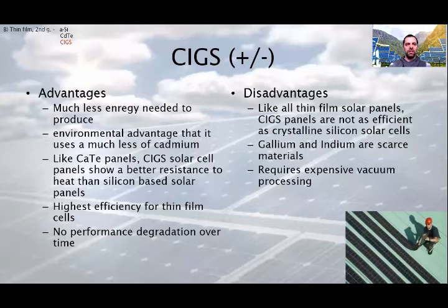As always, we evaluate its pros and cons. First, let's see the advantages of CIGS. The active layer CIGS can be deposited in a polycrystalline form directly onto molybdenum-coated glass sheets or steel bands. This uses less energy than growing large crystals, which is a necessary step in the manufacture of crystalline silicon solar cells.